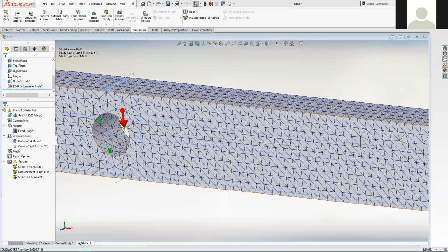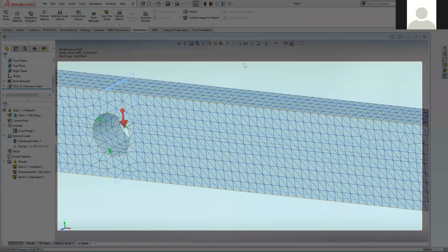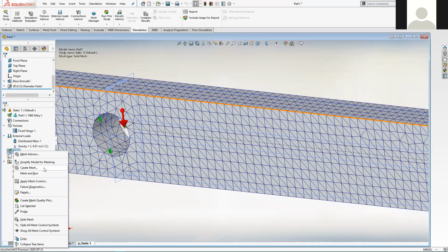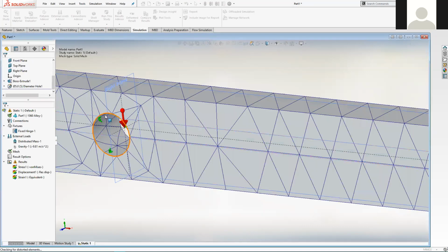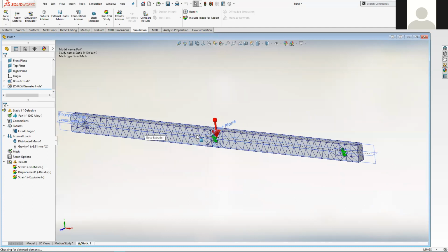So that's the broad outline. There's a whole lessons worth there in terms of tweaking mesh sizes and element shapes. And again, I've given you the really brief overview there, which is just slide this slider from left to right. That's as much as we're going to go into that at this point. But just know that what you can do is affect the mesh size as it comes into contact with certain design features in your design.